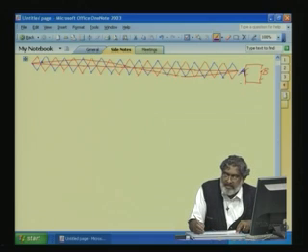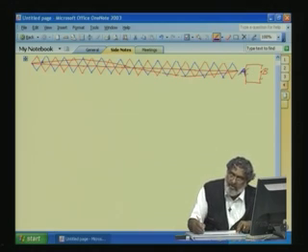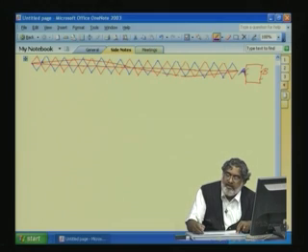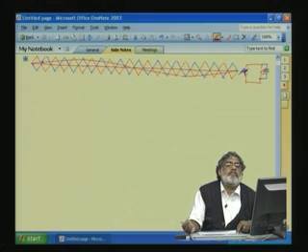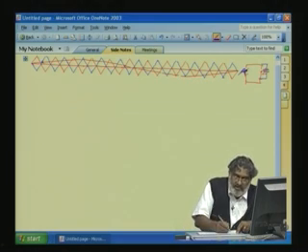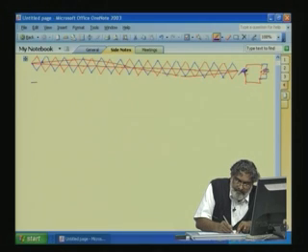And when the sine is less than the triangle, that means we are comparing the modulating wave and the blue triangle waveform. When the sine is less than the triangle, the bottom switch is on. So, when the top switch is on, the center point with respect to our DC midpoint is equal to plus VDC by 2. Otherwise, it will be minus VDC by 2.